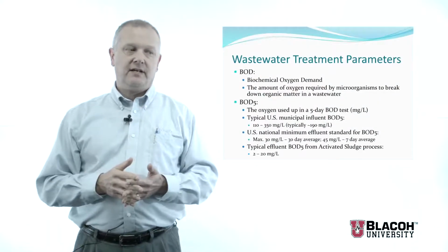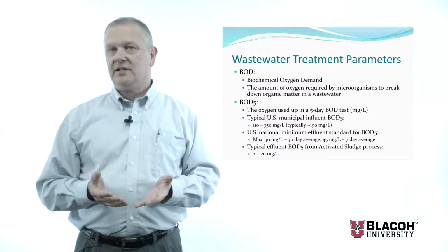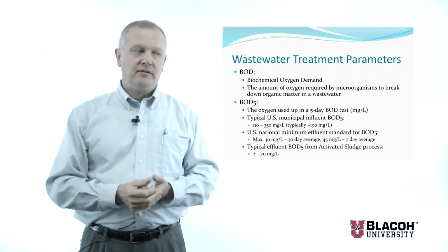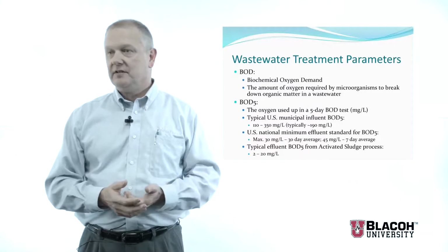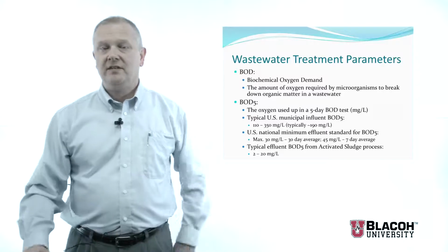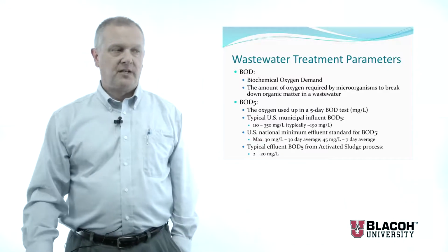And so the activated sludge process is helpful because from that process, typically we can get BOD down into the single digits in milligrams per liter or parts per million. So it's a very effective process, and it does a good job.